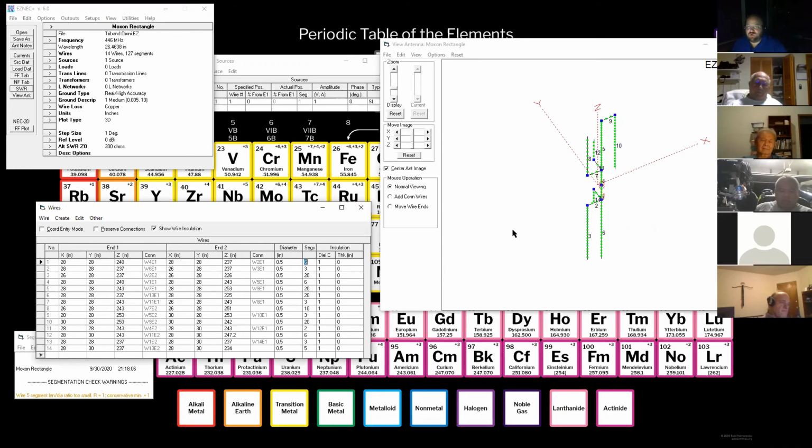It's actually a ratio based off of the wavelength, but just keep yourself to a rough 1 per inch for your VHF antennas. For a 160 antenna, 1 per inch isn't going to make any difference. The 160 meters doesn't care. You could run them 6 inches apart and you're going to get the same result.